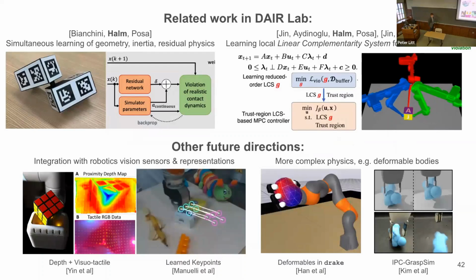Right. So there's two things I want to decouple here. One is, why do we use cuboid shapes? And this is a very nuts and bolts answer, which is that we were tracking them with April tags, and you need to put April tags on a flat surface. We do think that there are a number of different ways to transition away from that. We have some students working on using modern model-free object tracking with depth cameras to capture that data, and also fusing the point cloud data with the learned geometries. But there aren't any really compelling results in that area yet.